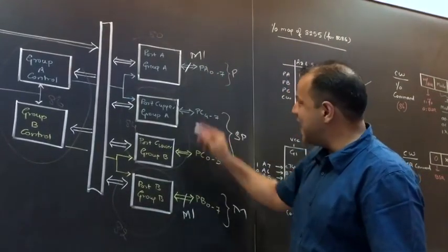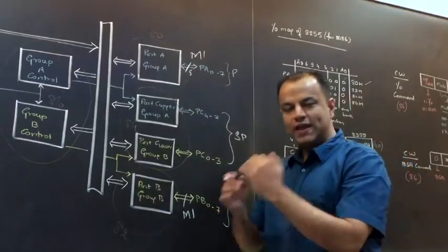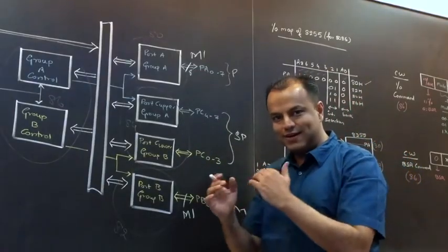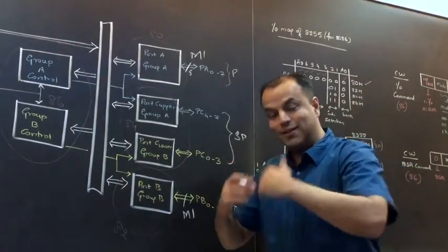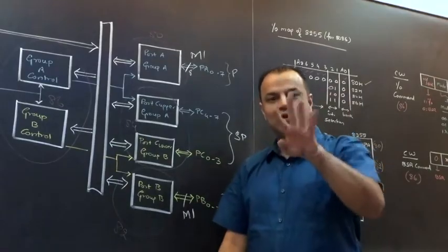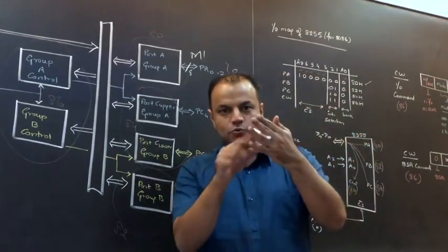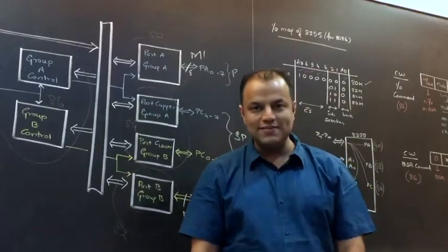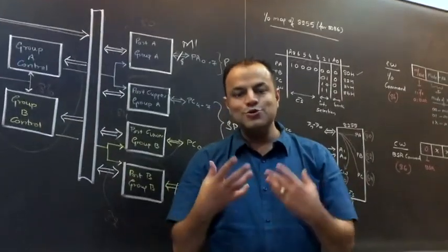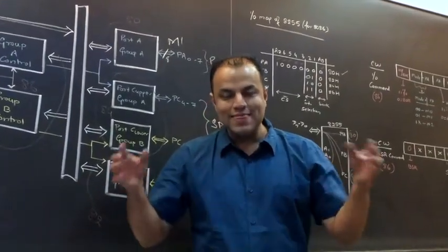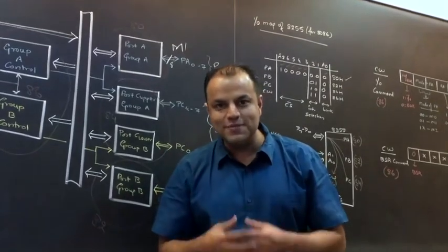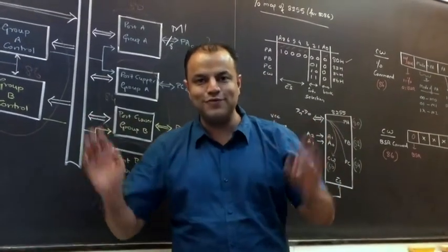The port has 8 lines. Those 8 lines will transfer data, no doubt. But other than that, you need 4 additional lines to perform handshaking. 2 on this side of 8255, 2 on this side. So where do these lines come from? That permission, that acknowledgement that I told you about, they are not going to fly in air.